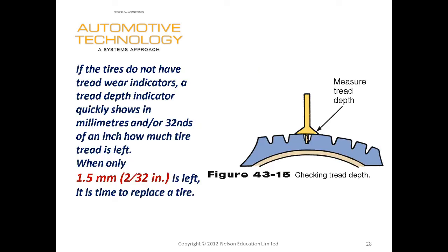Are our tires worn out? We can use a tread depth indicator to measure our tread depth. When only 1.5 millimeters is left, it's time to replace a tire. Yeah, this is good advice.